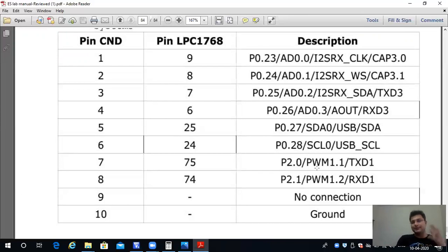After consulting appendix C, we confirm the use of port number 0, pin number 4 to 11. So port number 0, pin number 4 to 11 comprises a total of 8 pins. Those 8 individual pins should be for individual LEDs, and we want to control those LEDs through those 8 pins of port number 0.